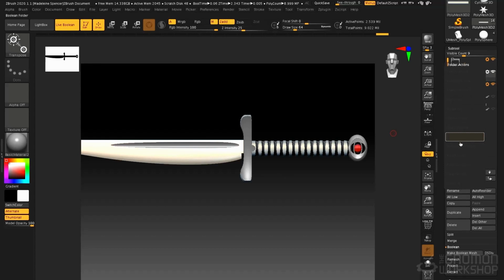And this should be the most accurate of them all because we have increased our resolution on those 2 Boolean objects, so the resulting mesh will be a lot more accurate. Also, it takes a little bit longer to generate, as you can probably see. It's just a byproduct of having extra divisions in there for ZBrush to do the math on what resulting mesh it'll get when it subtracts this model from this model. It has more points to compare.